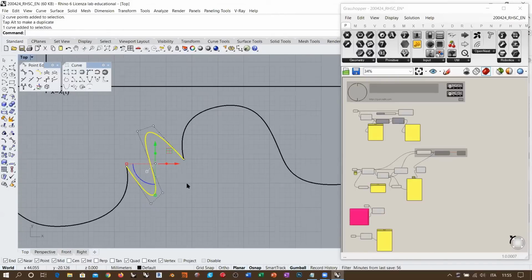Okay, so I can work with direct control point modeling. In this case, I cannot define exactly the precise continuity level from curvature up. I cannot do this. So I have to use utilities, which are, by the way, blend curve, match, and so on. But I can provide the right topological structure, meaning the right amount of control points in order for this curve to become tangent to the existing ones, okay?